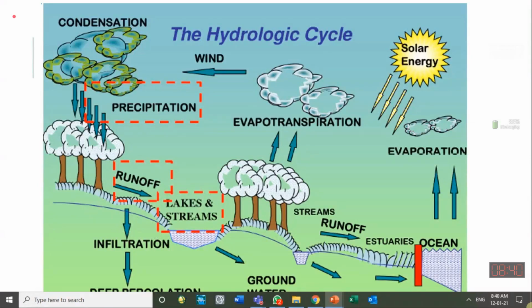Wherever there is a low water table, it moves towards that. Sometimes this water table line joins with the ground surface line. So over there we see springs with water coming out. (चश्मा जिसको कहते हैं, वो बाहर निकलते हुए नजर आते हैं.) That is actually the groundwater table visible at the ground surface level. So then we see the springs over there, and that also ultimately reaches the stream.